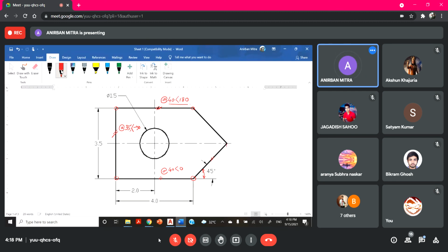Of course there is. I can make this construction. These two lengths would be same. So this is delta x. If I want to go from here to here, this is delta y. So I have the Cartesian relative command of @delta x, delta y. And in this case, delta x is equal to delta y because this angle is 45 degree. And what is this delta y? This is 35. Half of it is 17.5.